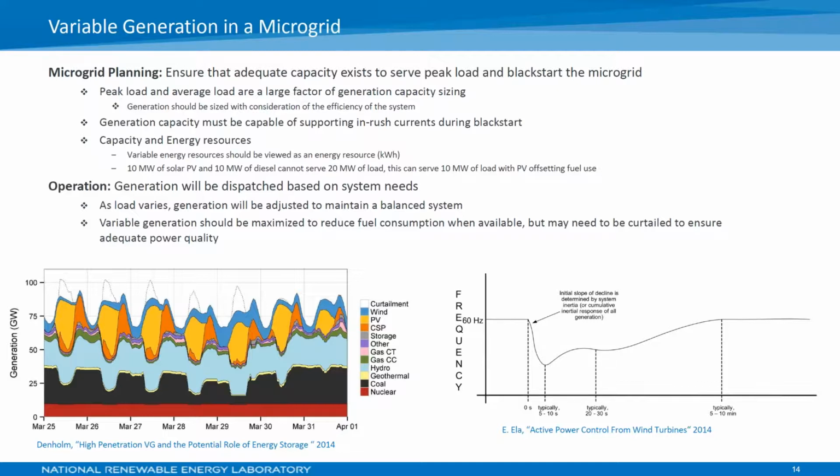If you have solar PV and wind sort of offsetting some of that diesel fuel, there's an inherent benefit that you don't need to store as much diesel on site, or don't have to have it shipped in as frequently, different things along those lines. But yeah, the challenge is that wind and solar are not like a capacity resource. If you have a 500 kilowatt diesel generator, you're going to typically get that 500 kilowatts if you need it. But if you have a 500 kilowatt solar PV array, it may not always be there. That's why, as energy storage is getting cheaper and cheaper, it helps to shore up that power that you could be getting from wind and solar to make it so that it's always there. And that doesn't devalue wind and solar. It just is a consideration that needs to be thought of as the system is going forward.